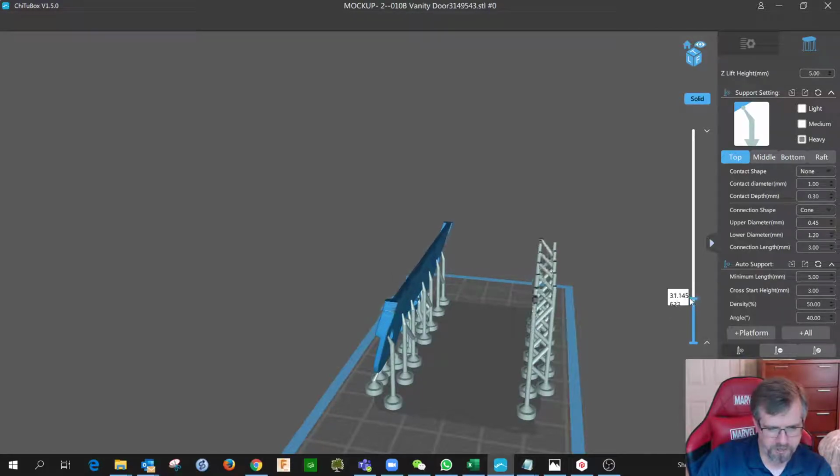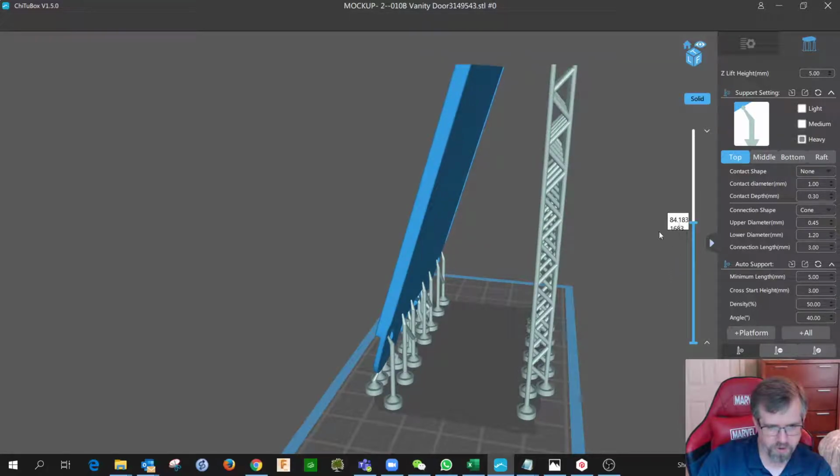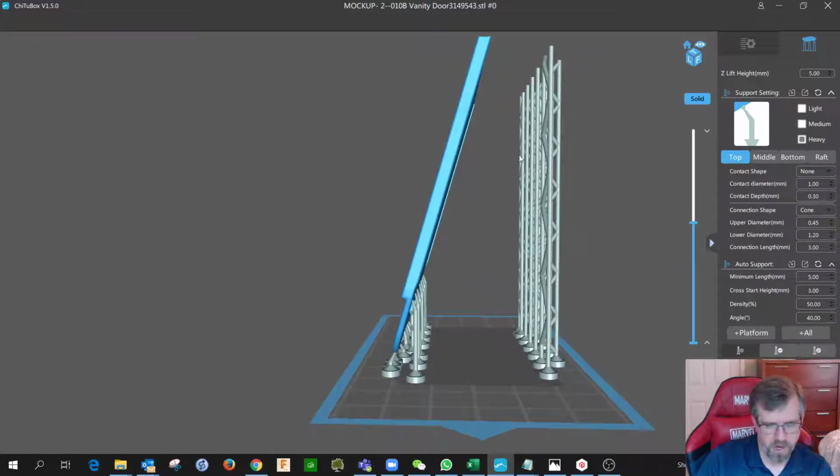As that image starts shifting over and over, think about how it's going to be pulling straight Z up right here, and then you come down here, there's nothing down here to pull against, so it's going to have a torque load over on these little spots. So there's a good chance that this whole plate is going to flex over and peel off, and again have nothing but print failures.